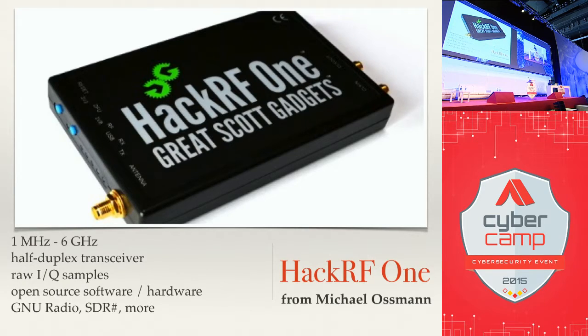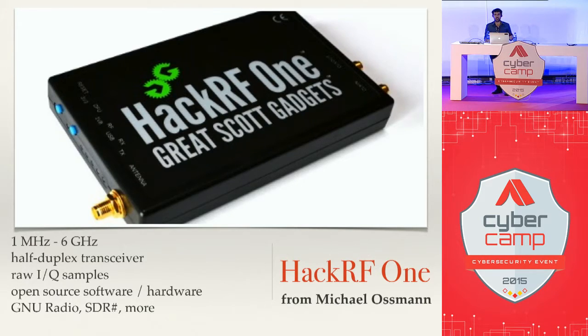You can get raw IQ samples. And what that means is you can basically get full raw radio communication. In quadrature, you can get not only amplitude, frequency, but also phase. So you can do anything with that raw data. It's also entirely open source, open hardware, and it works with GNU Radio.